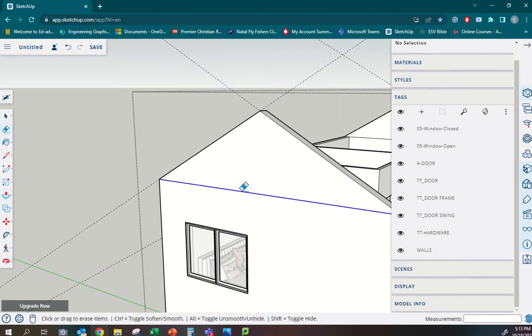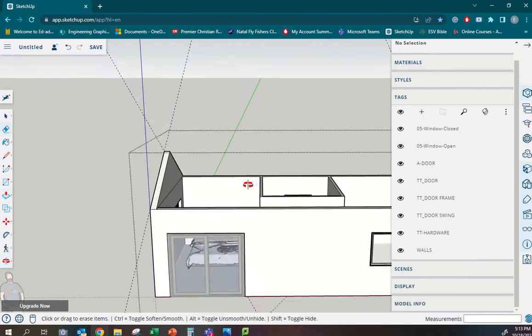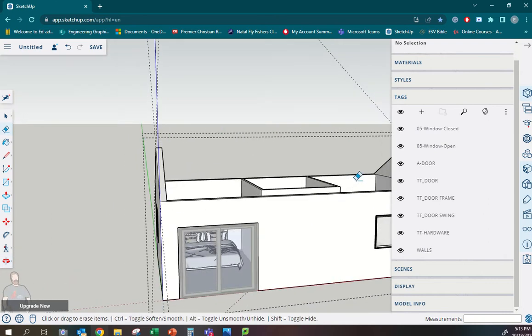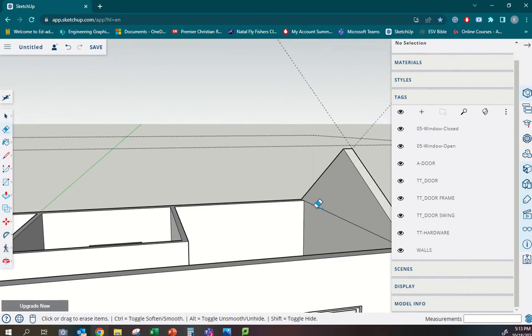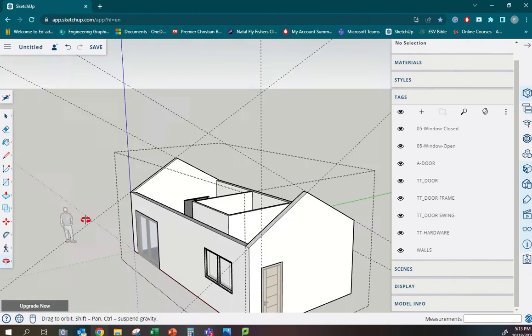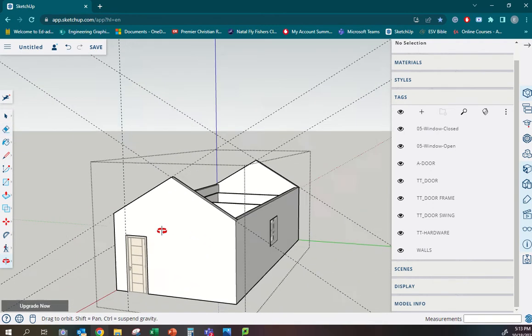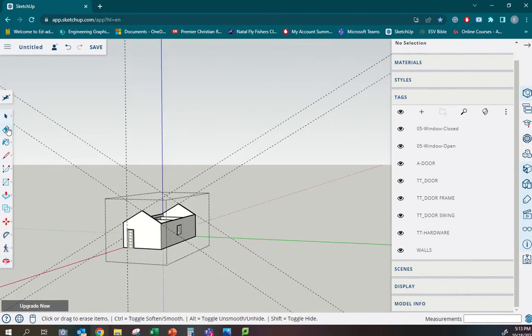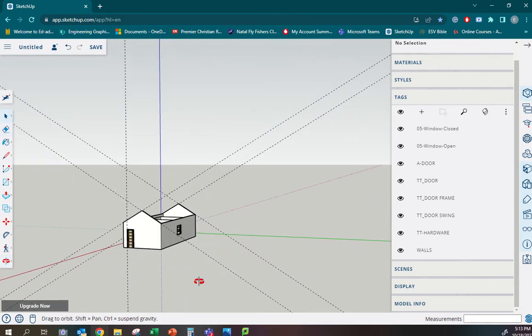And then I'm going to delete that line there because I don't need that. So what we have now, delete on the inside as well. If all my geometry is correct, we don't want a random line on the inside of the house. Right, there we go. So now we've basically elevated that wall up to create a gable profile, which is fantastic. Okay, so what I'm going to do here is exit this, and I'm going to create a new component.